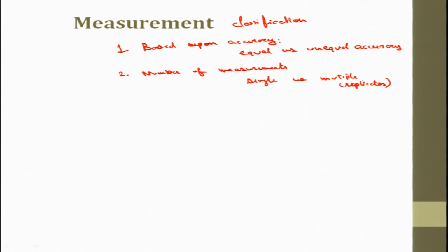So there are various ways to classify measurement. Another way may be the measurement based upon the technical measurement and metrological measurement. So the technical measurements are intended to obtain information on the properties of physical objects, processes and phenomena in the surrounding world, and metrological measurements are the measurements which we are studying in this course, and that ensure metrological traceability and required accuracy of technical measurements.